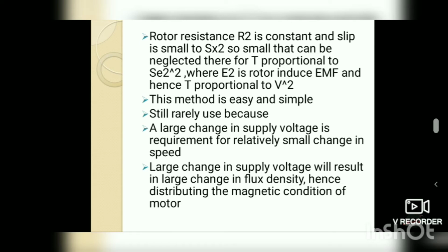So T is proportional to (s E2) squared, where E2 is the rotor induced EMF, and hence T is proportional to V squared.